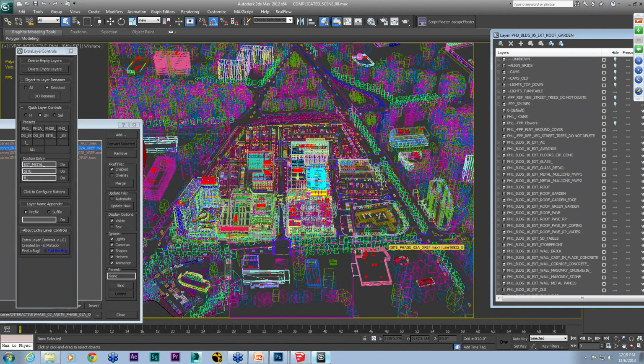In our studio, when we work with the Rhino models from the architects, we have a lot of problems with the normal faces when we import the Rhino. So we solve it by putting a shell modifier over the 3D model. Do you have another way to solve that problem?